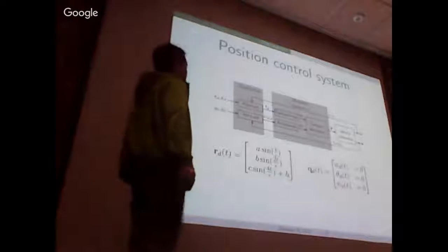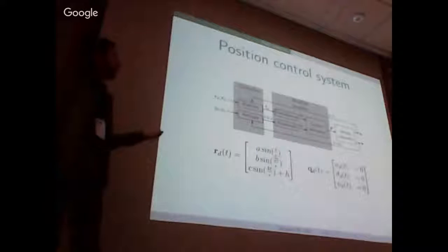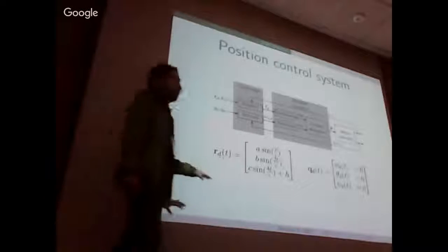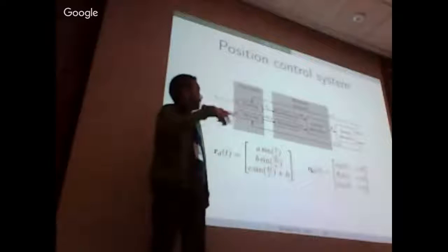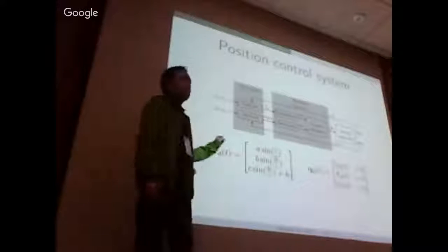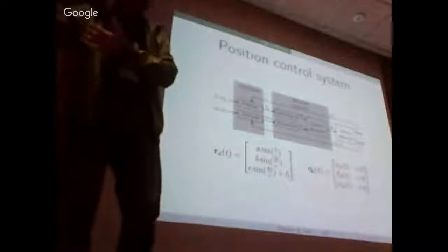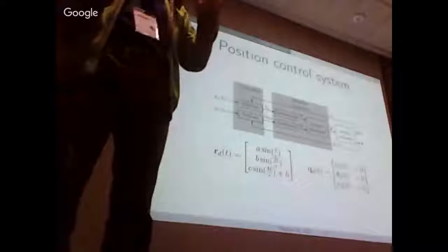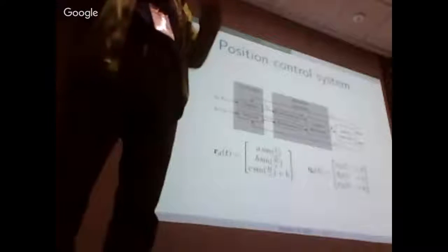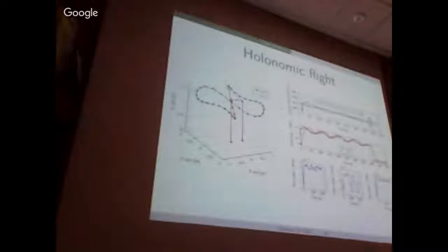Right? So this is how we designed the control architecture for this vehicle, and we made it describe a limit speed trajectory. What is different from the other approaches is that the translational and rotational dynamics can be decoupled because of the form closure characteristic of the vehicle. We can control the translational and rotational dynamics independently. Right? This is a simple simulation of the vehicle.